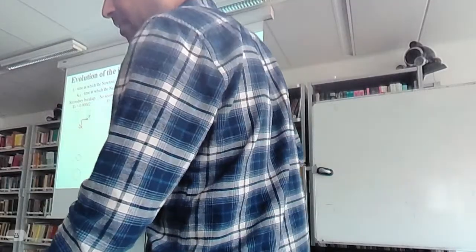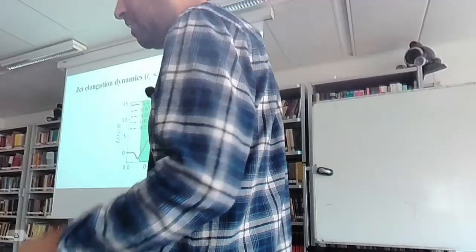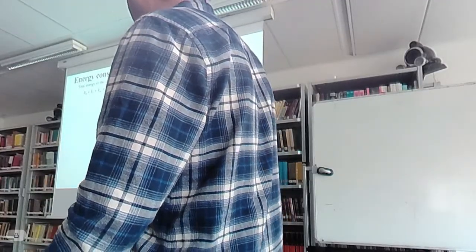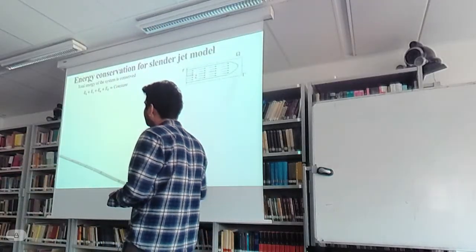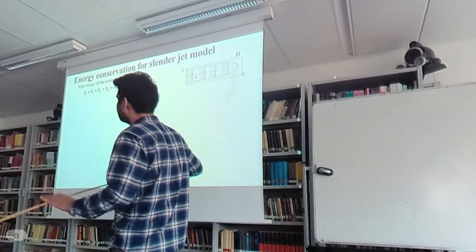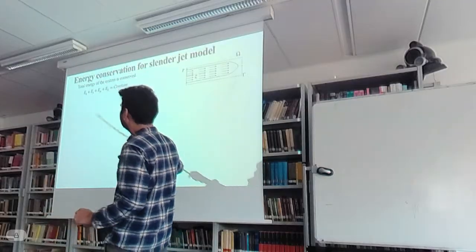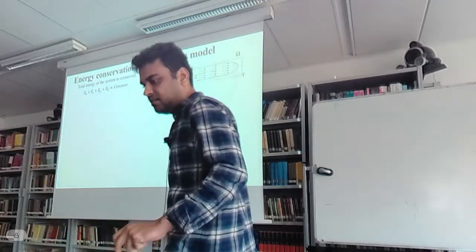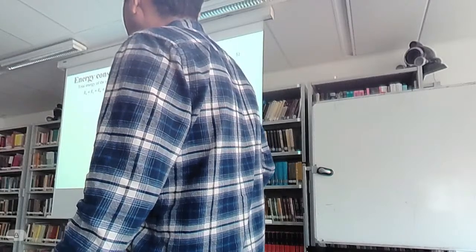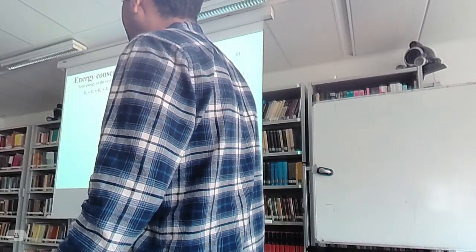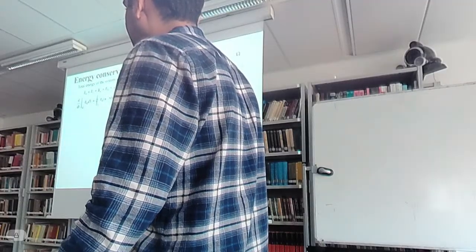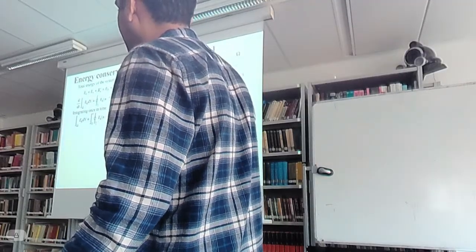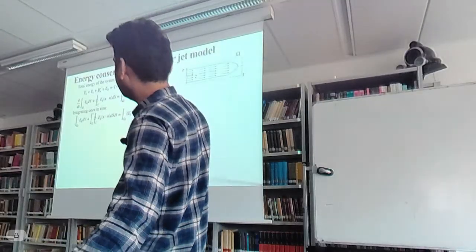So let's go to the first problem, which is the extension of the jet as it comes out of the nozzle. For this, I do some energy analysis. You have important energies in the system: the kinetic energy, the surface energy, the viscous dissipation, and the elastic energy, and they are conserved. I look at an ideal system where there is no dissipation, and I write the energy in transport form, which I can integrate in time, and I can have an evolution equation for kinetic energy.